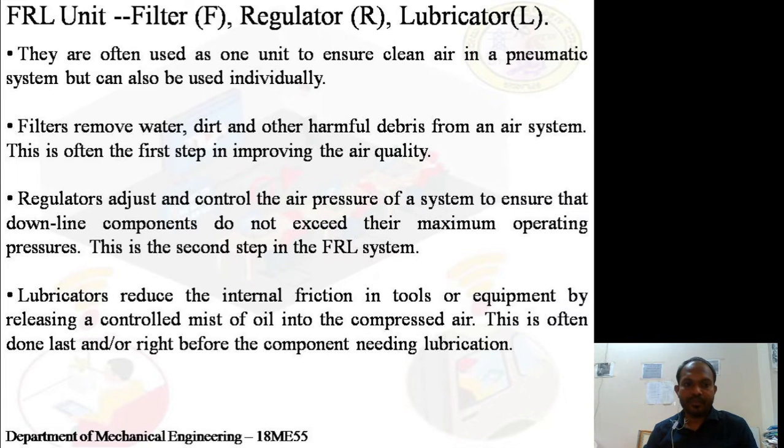Now the regulators are the ones which serve to maintain the pressure. It is something like maintaining the pressure of the air which is moving in the pneumatic systems at the right time. They can reduce the pressure coming into the system upstream while seeking to maintain a constant flow downstream. Ideally, the regulator should keep a perfectly constant pressure, but it is really difficult to maintain constant pressure from the beginning till the end.